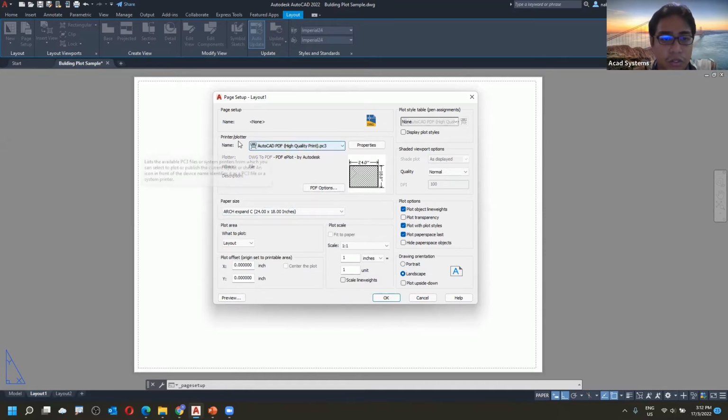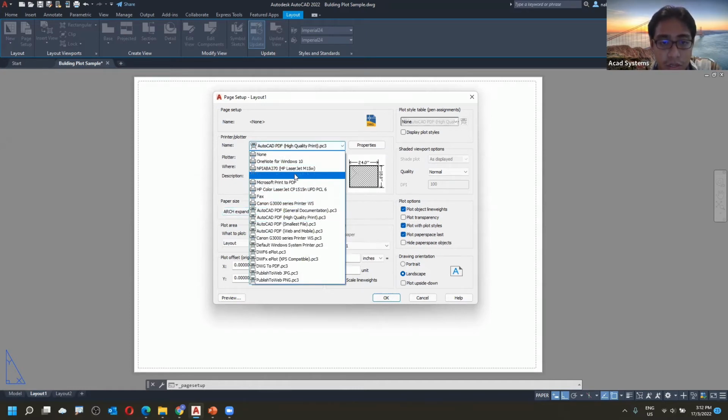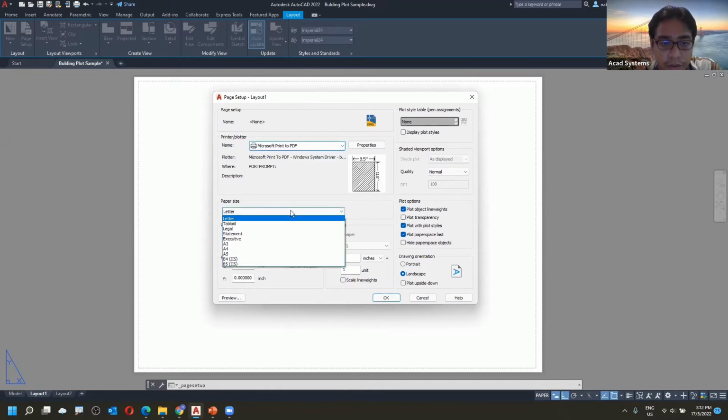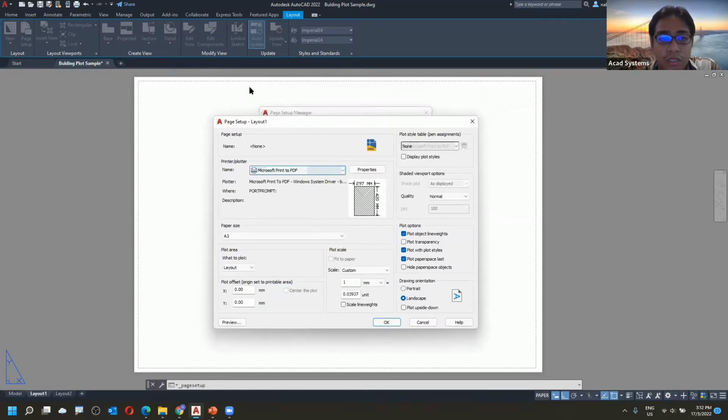Now for this case, I'm going to choose my paper size to be A3. So let's take a look and find A3. I'm going to print out the PDF, and I'm going to use A3. One thing you might notice is that on our paper size we have this dash line over here. Above this dash line, you will not be able to print, even though you have your image right above this drawing. That particular drawing will not be printed above this line. So make sure your drawing is inside this square dash line over here.